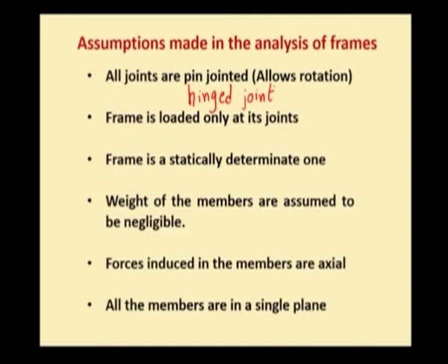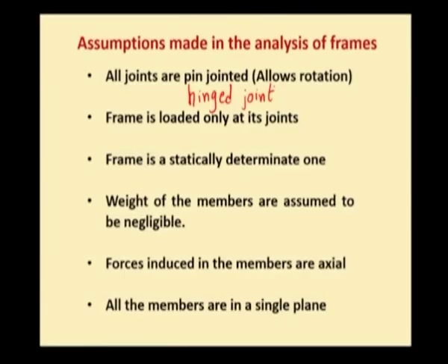The frame is loaded only at its joints. This we have seen already. So, no load will be acting anywhere in the intermediate part of the member. The load will be acting only at the joints. The frame is a statically determinate one. Weight of the members are assumed to be negligible when compared to the external load, and hence they are neglected.